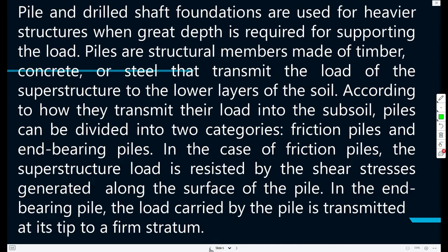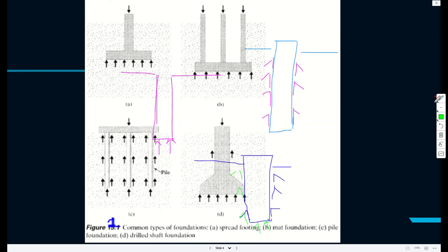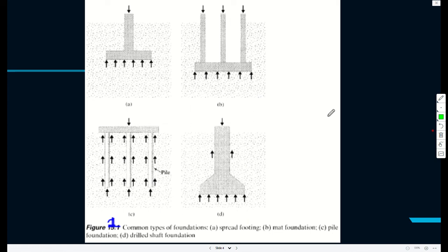Anyway, what we are saying here is, when you are boring or digging the piles, because the hole is sometimes unstable, depending on the type of soil or the type of material you are excavating, you usually put a casing.